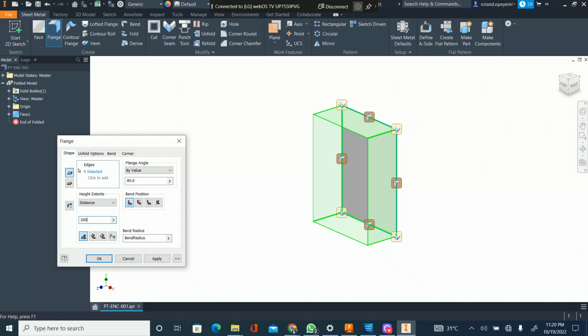That's the best way to bend these things. If we want to cut some clashes, sometimes we don't just design like this, but in some cases this kind of design works. So I'm just going to carry on. So the flange is going to be like this. So instead of putting this, I'm going to put a parameter nomenclature here, depth equals to 150.